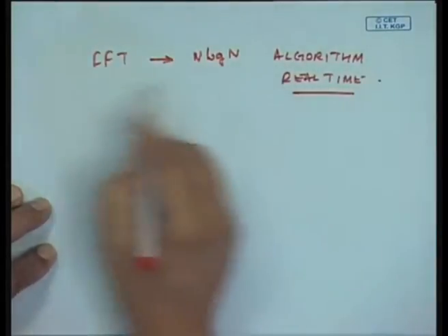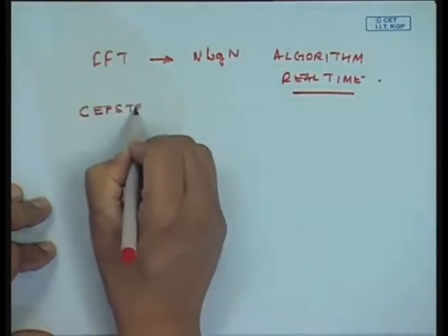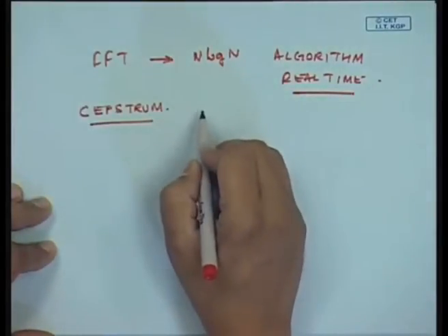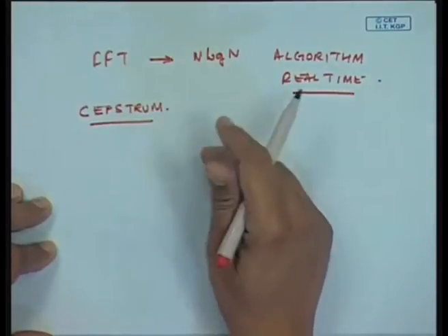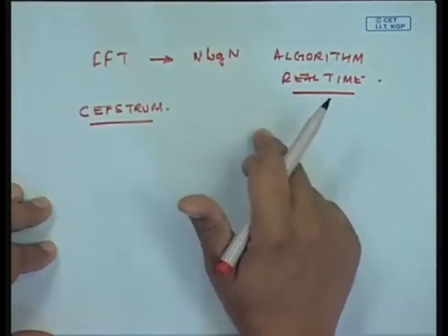Unlike FFT, Cepstrum cannot be done in real time, because a block of data has to be taken, and processed to find out their log amplitudes, and to find the unwrapped phase as a continuous signal. Once we have an FFT, then once you go for a Cepstrum analysis, there is software that will do this calculation for you, but it is not real time, it will take some time for computation.